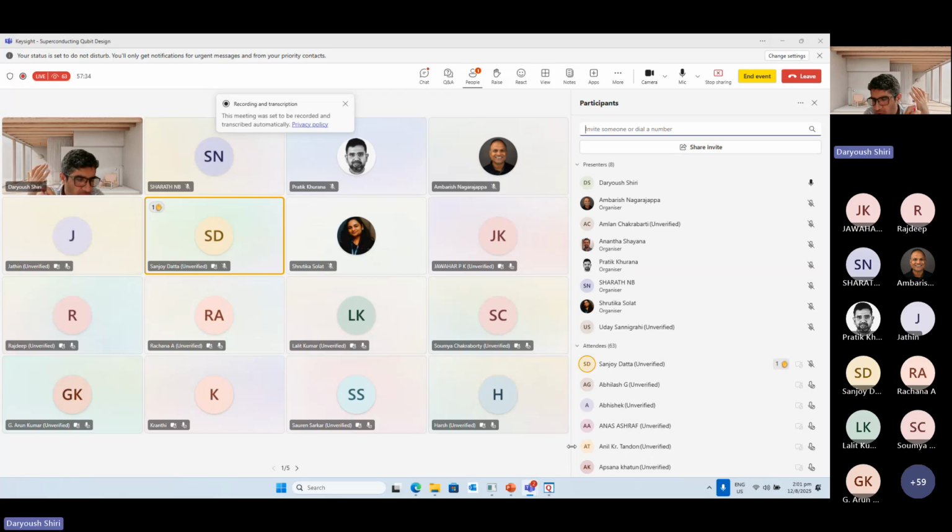For example, 2 or 3 years ago, Keysight did not provide a Josephson junction model. So in my research, I used a symbolically defined device in Keysight ADS, wrote the Josephson equations, and created my own JJ and SQUID black box. So in principle, it is possible in different ways. Either we can help you, or you can also do that yourself.